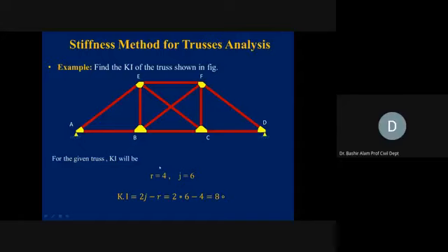Now, which ones are those 8 degrees? At joint B, it's a free joint, so it can translate to the left, right, and also up, down. So horizontal and vertical displacement, 2 from B, similarly 2 from C, similarly 2 from E, and 2 from F also. If you forget this equation, by observation you should be able to find the kinematic indeterminacy of the structure, dealing with the nature of the joints and supports there.